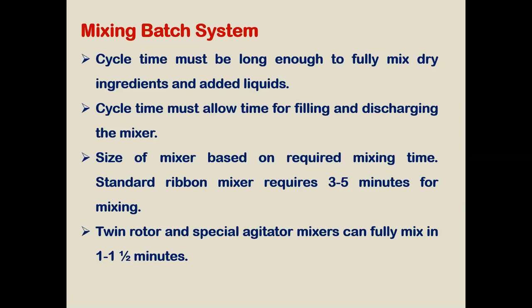Sometimes a twin rotor is also available in the mixer. A twin rotor with a special agitator mixer fully mixes the ingredients in 1 to 1.5 minutes. So with twin rotors, we can reduce the mixing time by almost 50%.